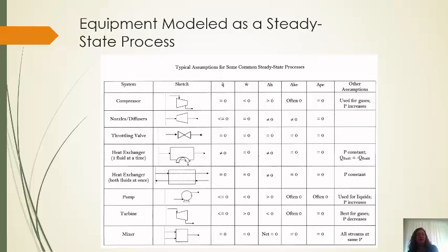There's not going to be any significant kinetic or potential energy changes generally, and so when I put my energy balance together with the first law, I end up with the net having no enthalpy change. But remember, each of these have different flow rates, multiple streams coming in and a single stream coming out. And so the net delta H is 0.